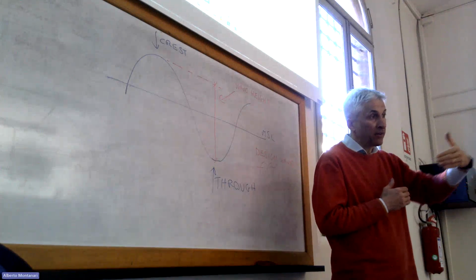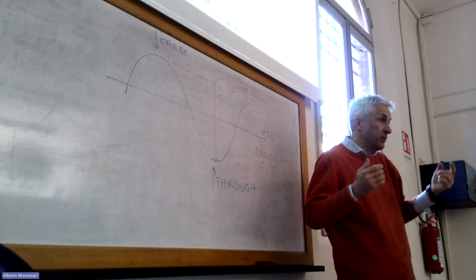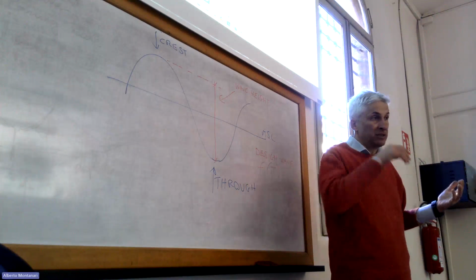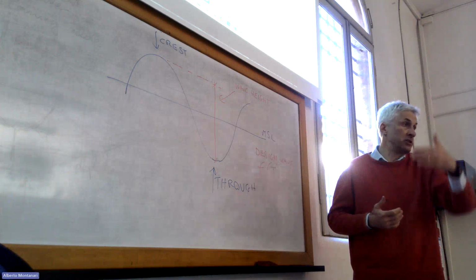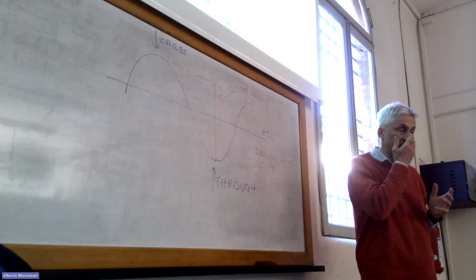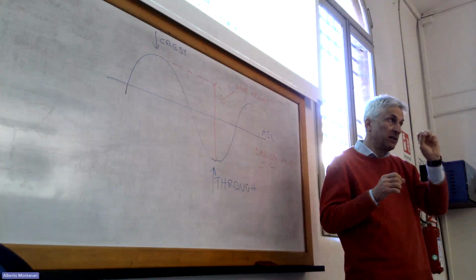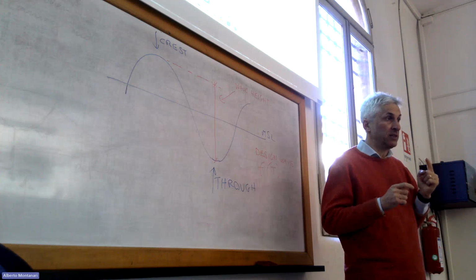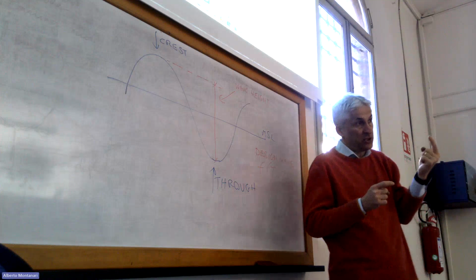Okay. Of course, you need to specify the minimum length of the observation period. Because it's clear, if you have an observation period of only 1 year, you cannot estimate the design wave with a return period of 30 years. You understand that? It's quite obvious. I mean, if I want to get an idea of the wave that may occur once every 30 years, I cannot get this idea from only 1 year of observations.